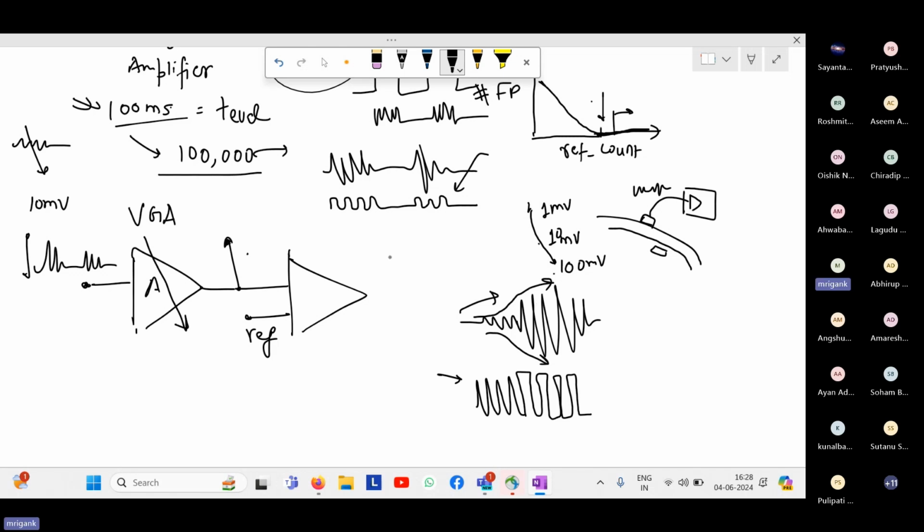So again, all those things are signal dependent. Based on the signal characteristics, you have to observe and set the gain. Suppose I have to cater to this entire range of signal, and after the fabrication of the amplifier and testing, we see that the actual signal coming from the sensor in the case of seizure is just 1 millivolt. Then I will have to do more amplification, and the variable gain needs to be increased. It will be set to a larger value.